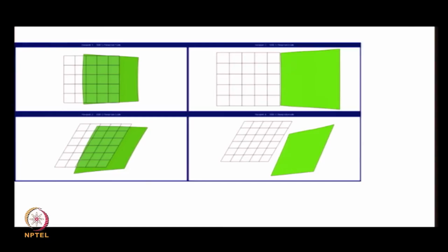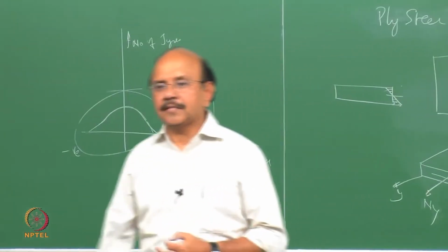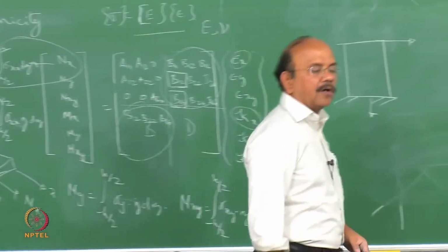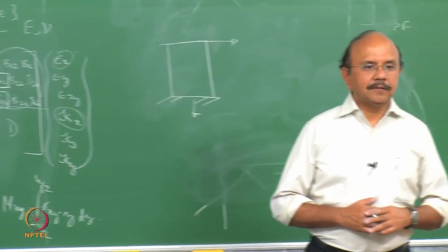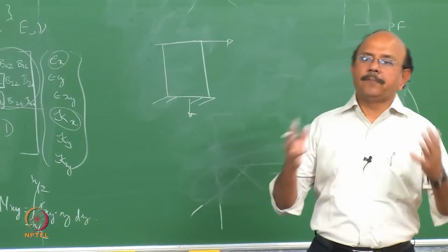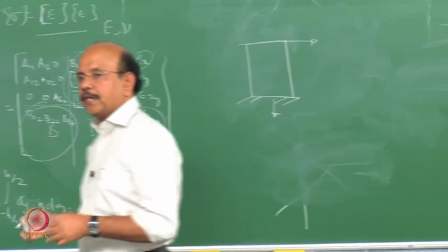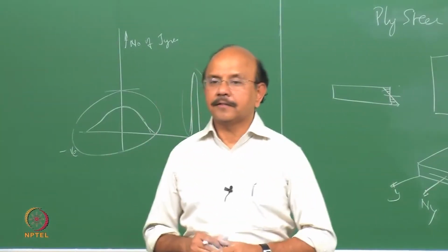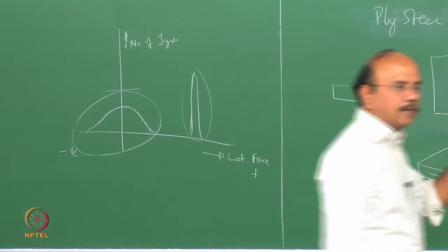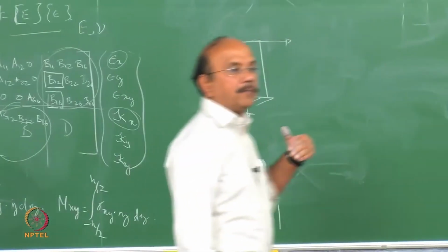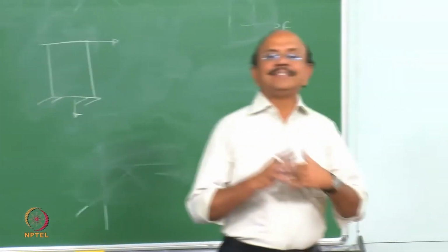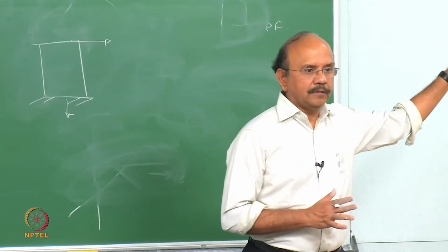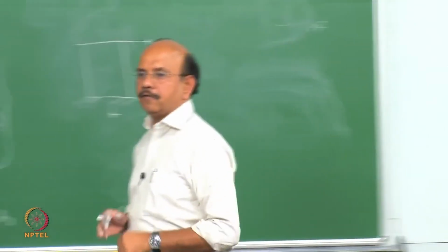Civil engineers long ago recognized this and called this unsymmetric bending. In fact, when you take this next course on automotive structures, we're going to talk a lot about unsymmetric bending. They realized that there are principal axis directions along which there is no coupling. And again, there's a coupling factor involved because I am not applying the force along the principal axis direction, which happens to be the symmetric axes, that you see, for example, in the first picture.